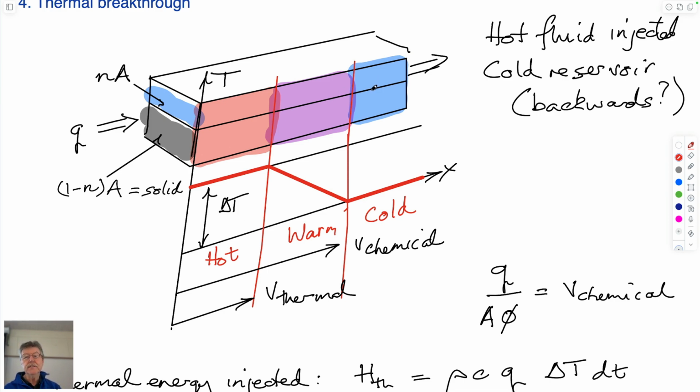So the point is that there'll be the hot fluid you put into the cold reservoir. It will rob the coldness from this area and pull down the temperature of the fluid, but that cold region at the beginning of the inlet will slowly be raised in temperature by the hot water that's dropping its temperature in that zone.